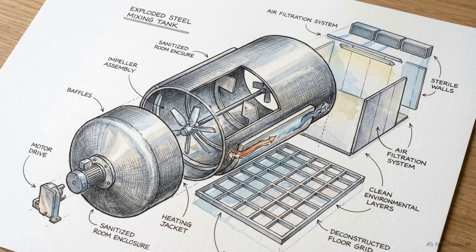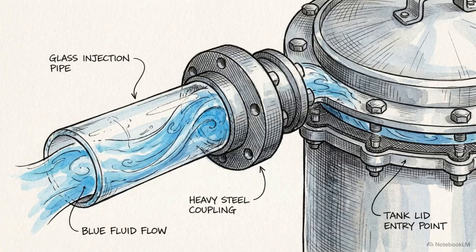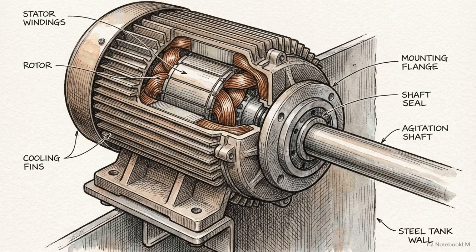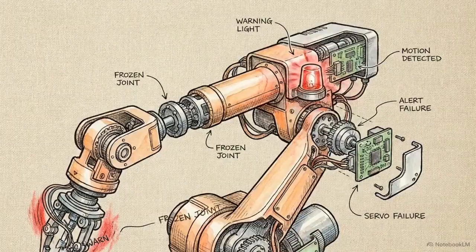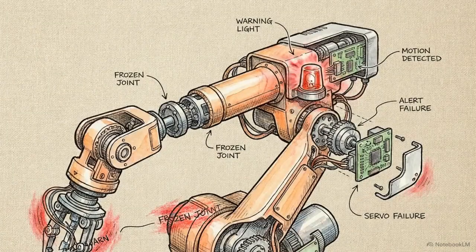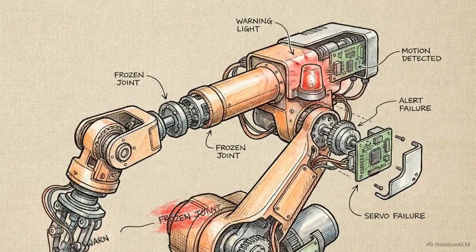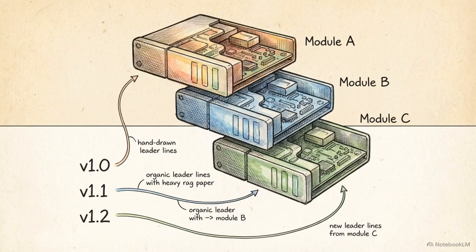In a pharmaceutical batch mixer, for example, a single PLC strictly orchestrates the temperature parameters, the exact ingredient sequencing, and the agitation speed. Because the PLC executes its logic in a perfectly rigid, unbroken cycle, the resulting continuous process is highly repeatable and legally validated. Complex scheduling and heavy mathematical optimizations are deliberately excluded from this layer. Processing those tasks would interrupt the critical fast loop and delay actuation. When logic updates are required, engineers rely on modular program structures and tight version control, minimizing the risk of introducing errors into the physical operation.